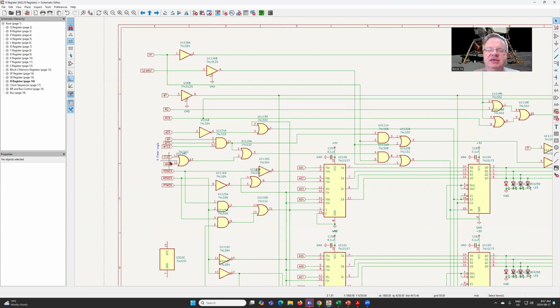Now, there's one other control pulse that we haven't talked about. It's the CLXC, which is a control pulse that works with the branch register. There are two branch registers used for program control, and if the CLXC control pulse is asserted and BR1, the branch register 1, is set to 0, we will clear and reset the X register. So it's the clear X register control pulse. What we'll do first is talk about the circuitry to reset or clear the contents of the X register.